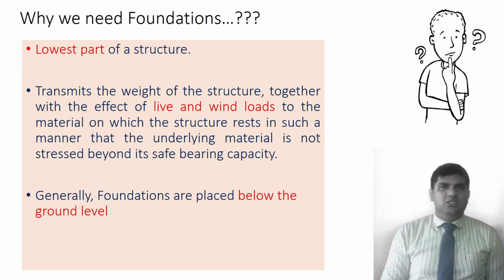The foundation is mainly used to transfer the load to the firm soil strata or firm soil layers, or we can say into the bedrock. Especially in high-rise buildings, we are using pile foundations. Then in the pile foundation, the loads are going to be distributed into the bedrock.